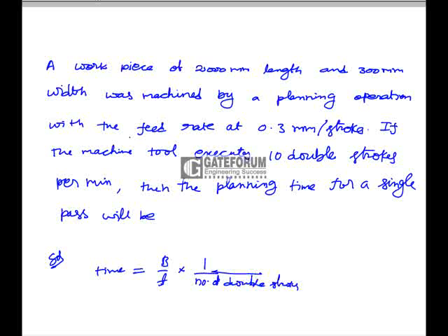So here width is 300 mm and feed rate is 0.3 mm per stroke, and here 10 double strokes per minute, which gives the value of 100 minutes.